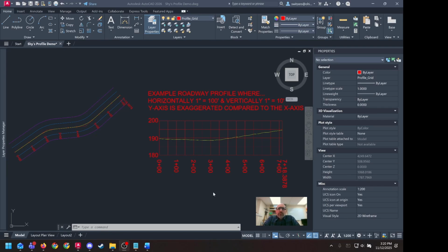On this episode of the Civil Basics series, part 5 of 6, we will use a standard version of AutoCAD 2026 to generate a roadway profile or vertical alignment within our model. In this video, I will cover what is a roadway profile, how to set up the grid, determine spacing, and determine the X and Y values, how to automatically generate the profile line and block it into AutoCAD, and how to insert this profile into model space and scale it to fit your grid.